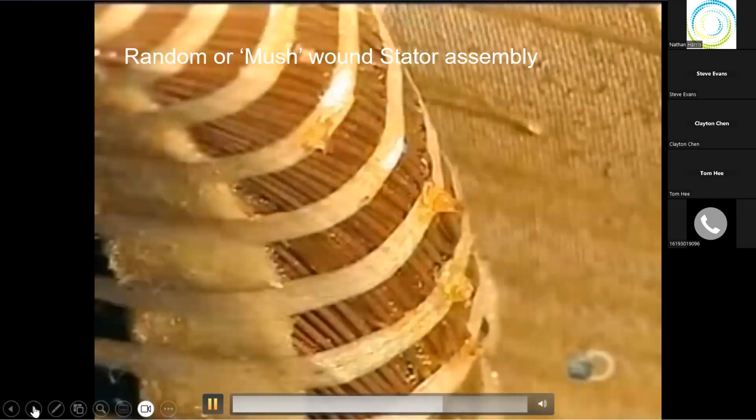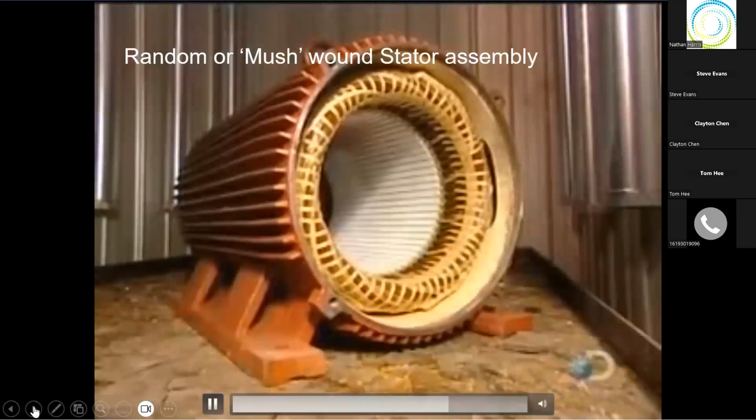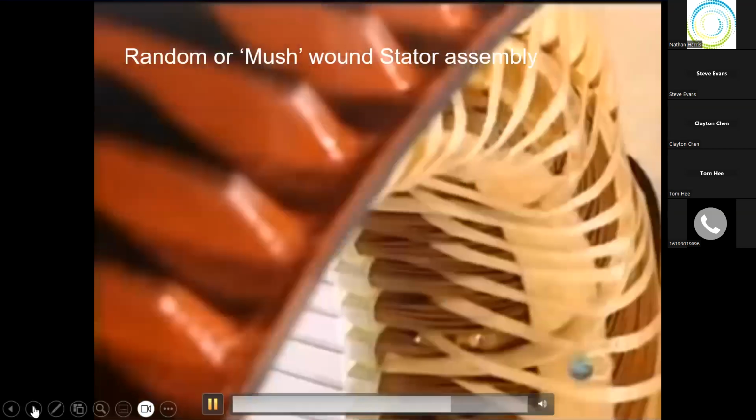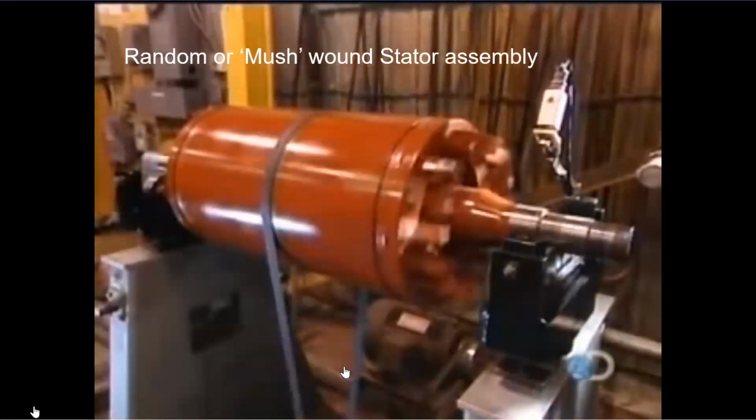The stator is put into an oven for 6 hours at 280 degrees Fahrenheit. The varnish hardens, making the stator coil rigid. Now they have to balance the rotor.